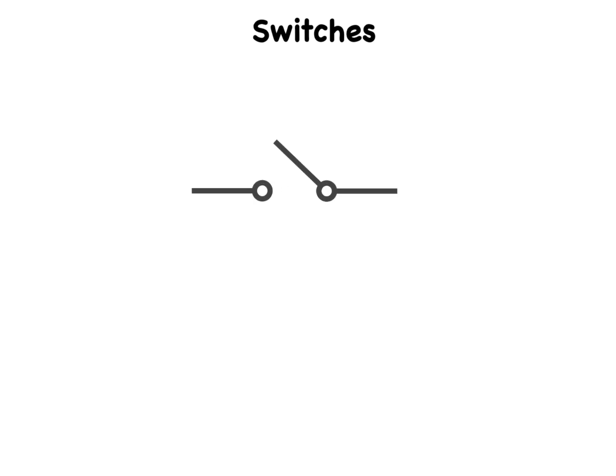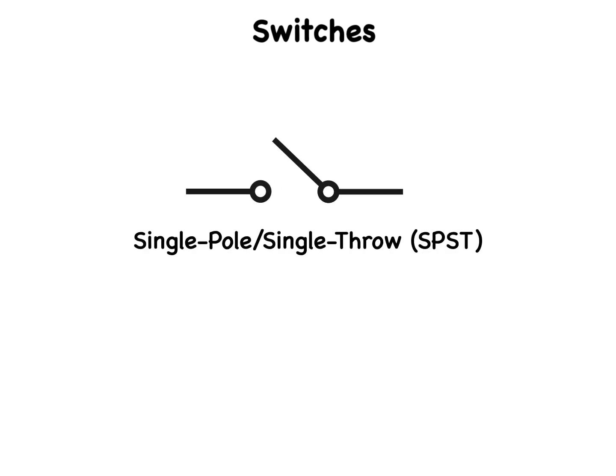A switch is a device, mechanical or electrical, that completes or breaks the path of current. Additionally, a switch can be used to allow current to pass through different circuit elements. The schematic symbol for a single-pole single-throw switch is illustrated here. This component can make or break a contact at only one point in a circuit. It's a two-position device, on or off, alternatively, make or break.